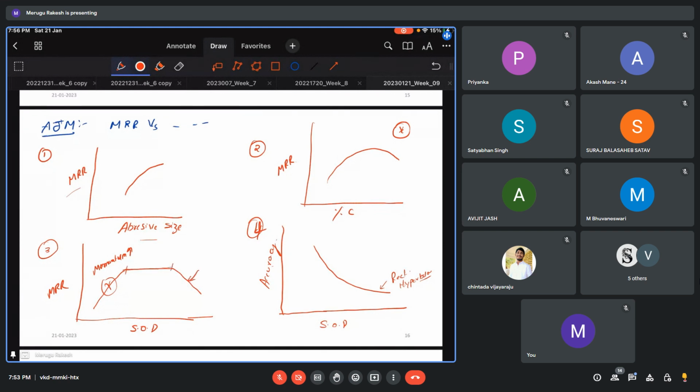But in this area, the drag will influence, so that the particles that are coming out cannot, after traveling a certain distance, say this value, point C, point B and point A. When it travels this much distance, there will be so much drag that it has less movement, so it will not effectively remove the material.